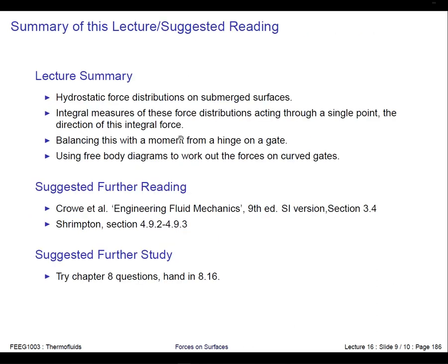Okay, so we've dealt with forces on submerged surfaces, both planar and curved. With planar surfaces, it's relatively okay. We just do an integral along the planar surface. For a curved submerged surface, what we have to do is take a volume where that curved surface is part of the surface of this sub-volume, and do a force balance on that particular volume.